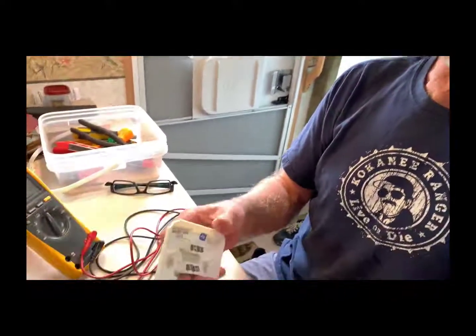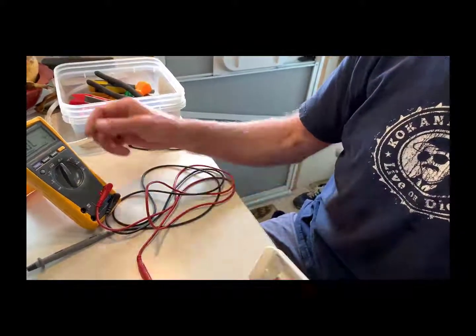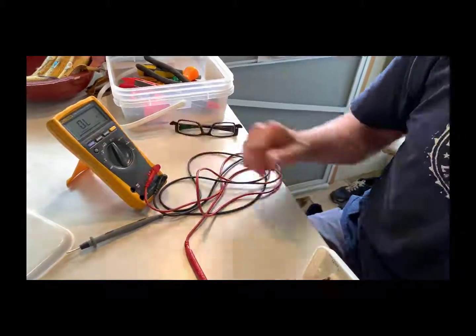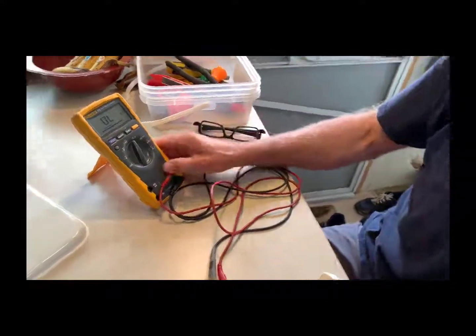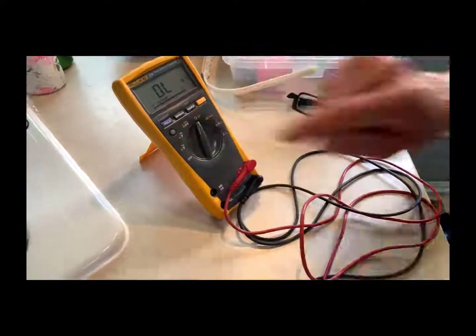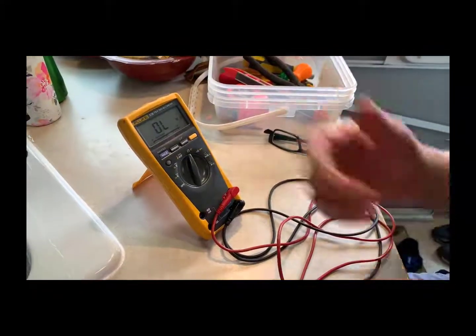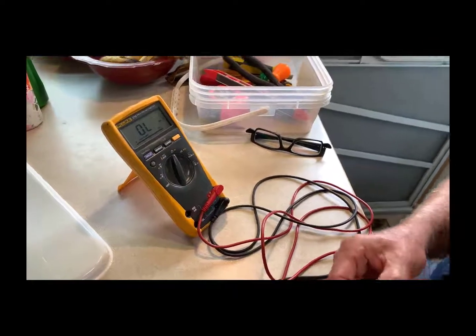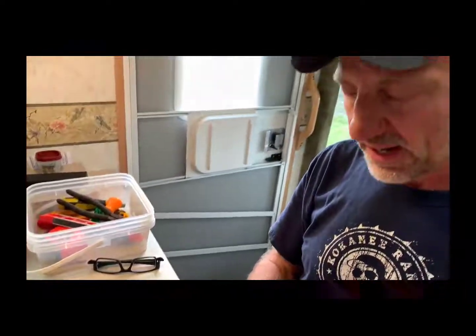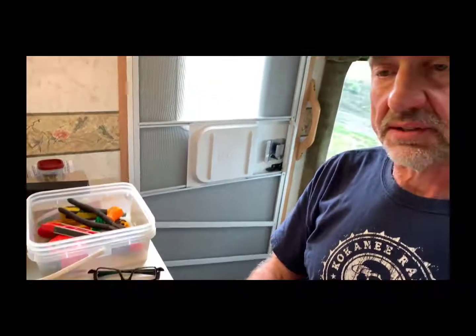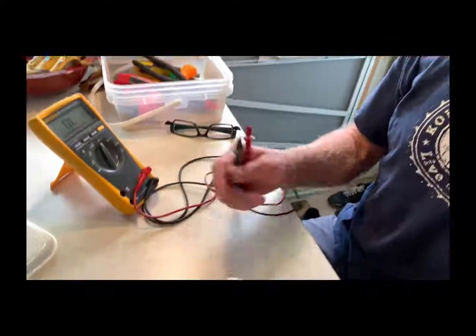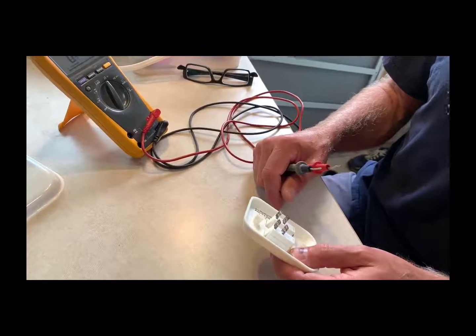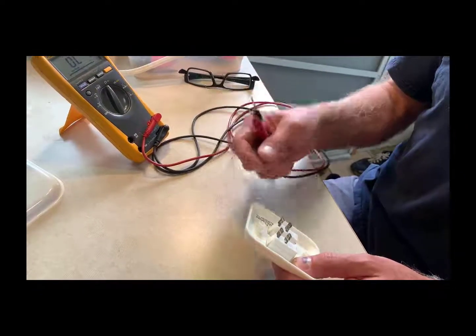What we're going to do is take a look at their on-off conditions in terms of resistance using an ohm meter. So I've got this meter set up as an ohm meter. Remember, you can follow the LFR rule there. We have the leads in the right place for an ohm meter. We have the function switch set for ohm meter, and of course it's an auto ranging meter, so we're okay on the range part of it. Now, if I'm going to look at resistance for any component, I've got to make sure that the component is not powered up or connected to any circuit. You can see here we're not connected to any wires or any source of voltage, so we're safe to be doing a resistance measurement.